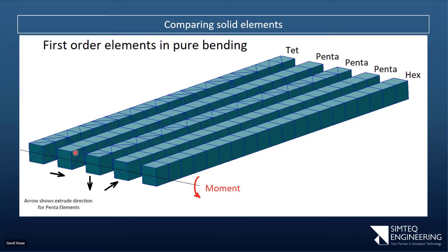This one, if I look at this face, that triangular face cannot have a gradient. So on that, in theory, there may be a gradient, but not in the direction we're actually interested in. But both of these, because the quad faces are on the sides, can actually have a gradient through the thickness. The last one is simply the X mesh.